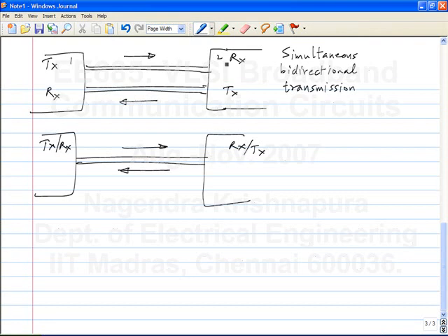Okay. What is the disadvantage of this? More wiring. Basically, you need more hardware in this case. That's the disadvantage. So for instance, you can have a PCB and you need now double the area on the PCB to transmit it both ways. And remember, you can have a large number of these things. I am not implying that there is only one transmitter and one receiver on each side. Okay. So there could be lots of them, and it needs more hardware.